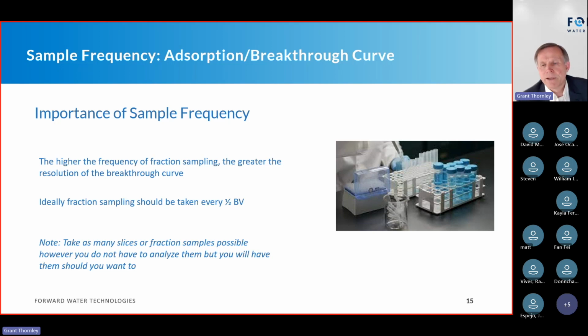analysis. Because people say, well, the more sampling I do, that's a higher cost. Not if I haven't sent it out for analysis. You're right. However, and I'd really stress this, when you're doing your enhanced testing, your fixed column, ask the DLE provider or have your technician take fraction samples every half bed volume and store them. Because later on, maybe you want to go back and develop a really, really high resolution breakthrough curve. Well, I don't have to rerun the test. I'll just run the analysis with what I have.